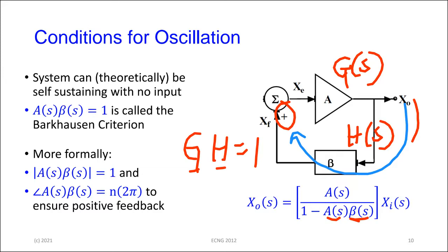Remember, in-phase signals add. So if you have two signals and they're exactly in phase, then when you pass them through the circuit, one is going to add to the other and the amplitudes increase. If they are totally out of phase, then they cancel. And if they're not exactly in phase, then you get some other funny behaviors, and the system will generate, as you know already from your physics, something called beats. That was the process of generating beats.